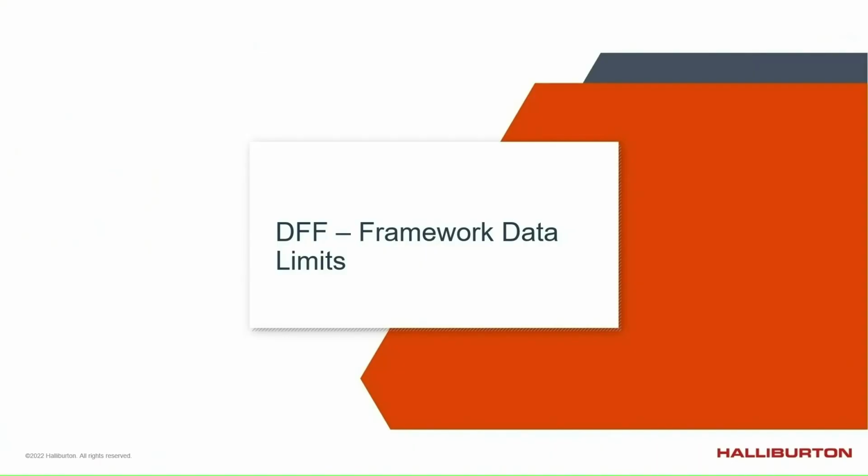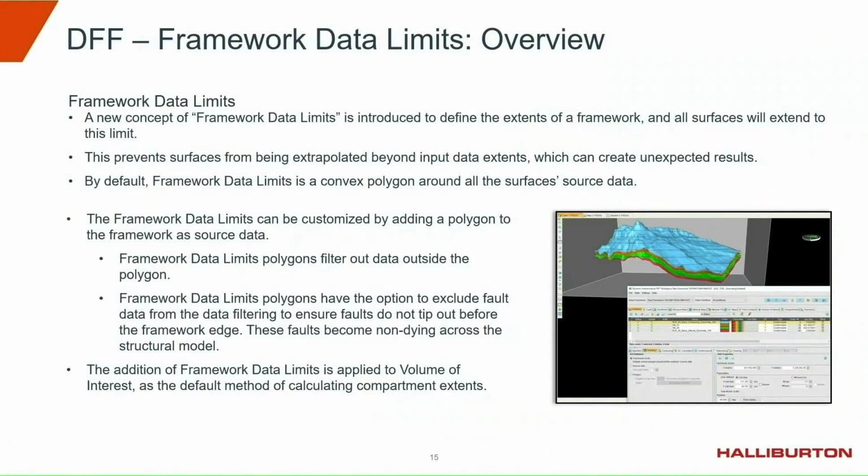Let's introduce the concept of framework data limits. Framework data limits explicitly defines the spatial limits of a model. So now the extent, size, and the shape of the framework is predictable. By default, the framework limits will be the convex polygon around all of the combined surfaces' source data. It can also be a